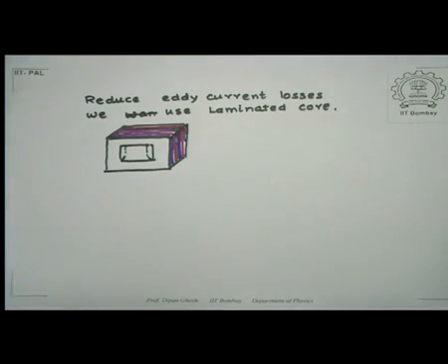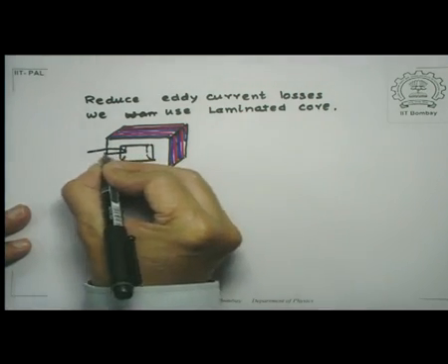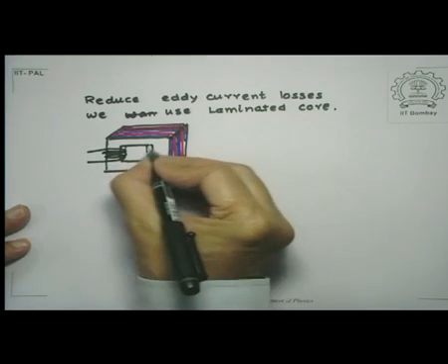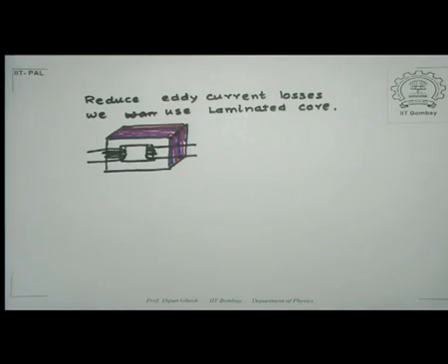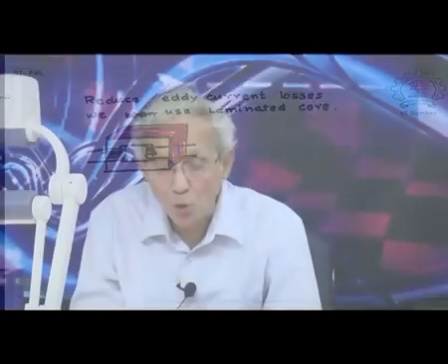And of course, likewise, I have this section, and here my windings are there. These layers or laminates are glued to each other by thin insulating coatings, and this helps reduce the eddy current because the thickness of each individual layer being smaller, the available area for these currents becomes smaller, and as a result it reduces the eddy loss.